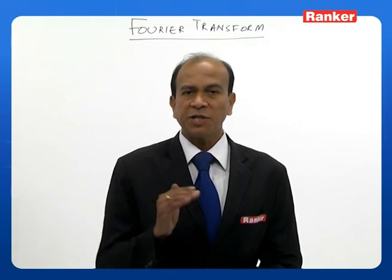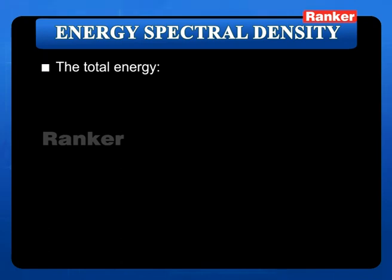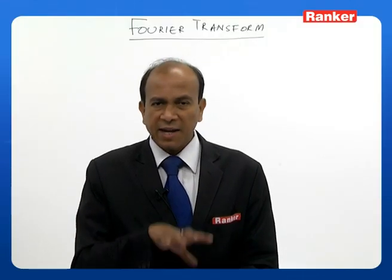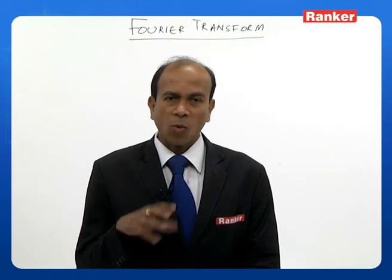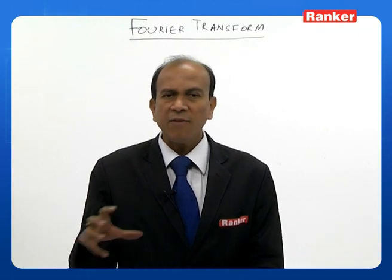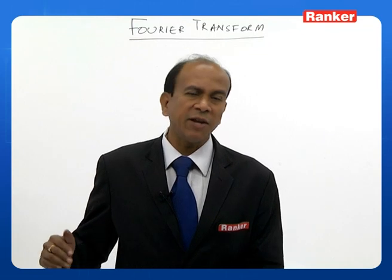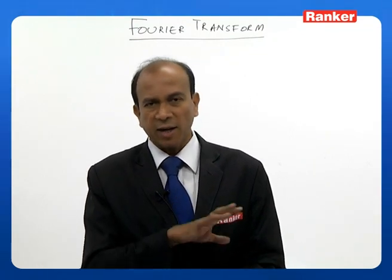Now let us look at energy spectral density. So what does energy spectral density say? The total energy E is given by, as you see here, integral from minus infinity to plus infinity mod g of t whole square dt. So that will again be equal to integral from minus infinity to plus infinity mod G of f whole square df. So this is the energy under the curve. If I calculate the area under the curve, that area will give me the total energy of the signal, whether it is in the time domain or the frequency domain. So these two will give us the total energy.